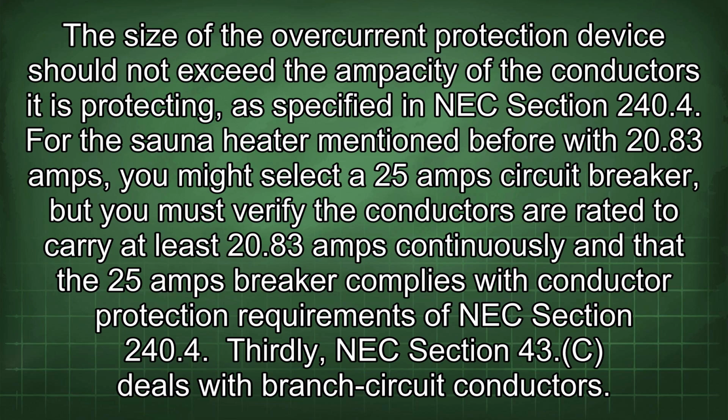For the sauna heater mentioned before with 20.83 amps, you might select a 25 amp circuit breaker, but you must verify the conductors are rated to carry at least 20.83 amps continuously and that the 25 amp breaker complies with conductor protection requirements of NEC Section 240.4.